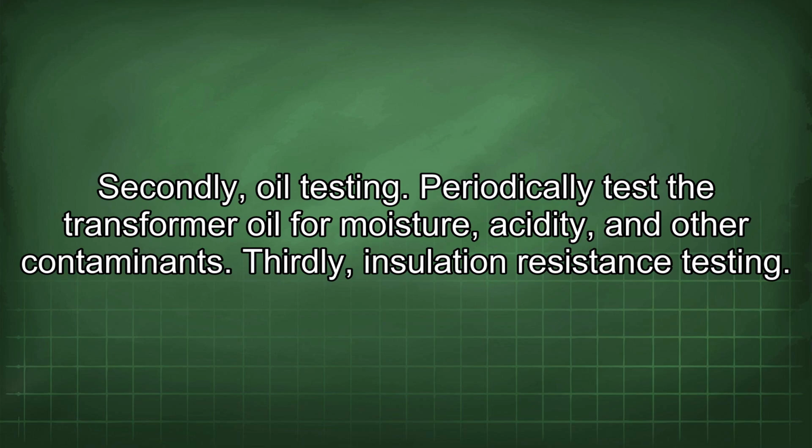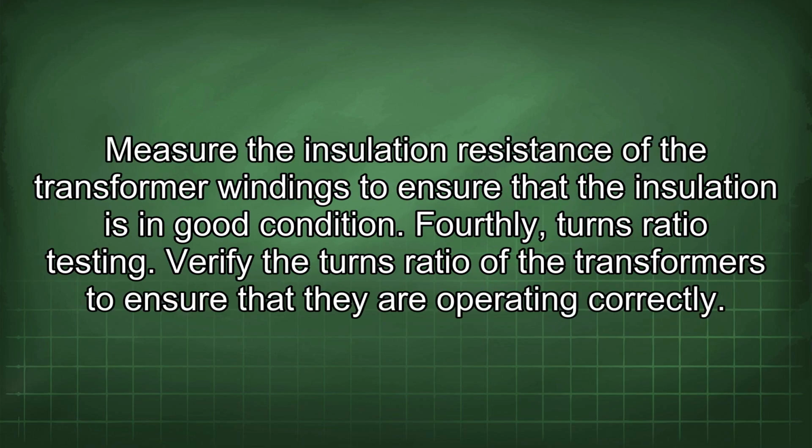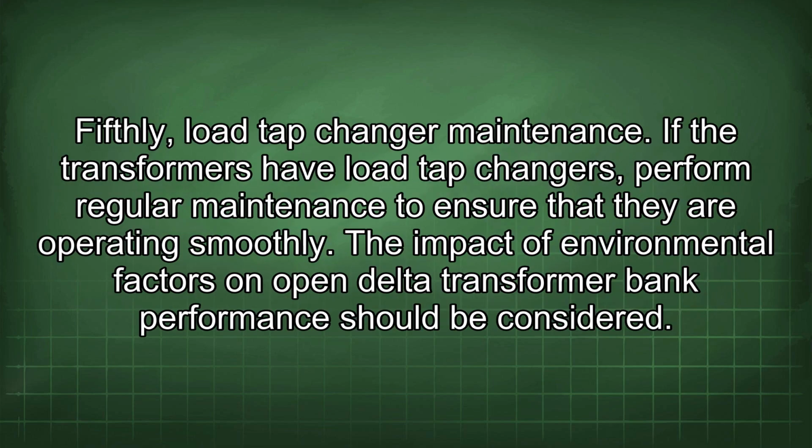Thirdly, insulation resistance testing. Measure the insulation resistance of the transformer windings to ensure that the insulation is in good condition. Fourthly, turns ratio testing. Verify the turns ratio of the transformers to ensure that they are operating correctly. Fifthly, load tap changer maintenance. If the transformers have load tap changers, perform regular maintenance to ensure that they are operating smoothly.